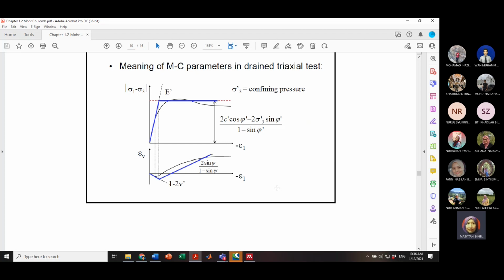How do we know whether the dilatancy angle plastic potential occurs or not? One way is when you have an associated flow rule, where the dilatancy angle is equal to the friction angle. That is the condition where you have the associated flow rule. If you have a different dilatancy angle, with a different value from the friction angle, we call it non-associated flow rule. It means the friction of the material and the dilatation of the material will behave differently in plastic conditions.